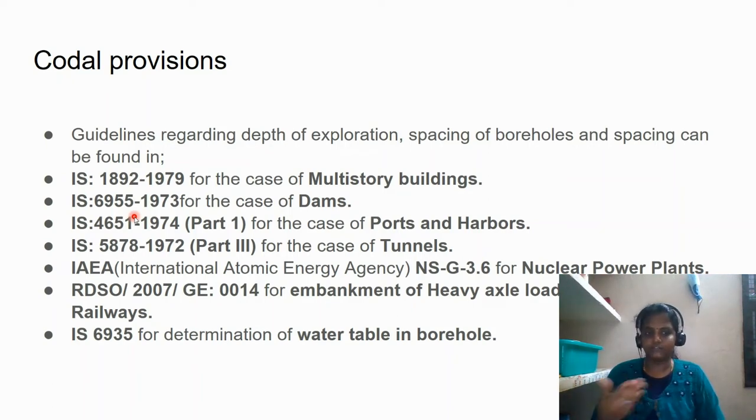And also, if you are able to encounter the same strata in three boreholes, of course you can stop at three boreholes. No need for the fourth one. So all these guidelines are subject to the judgment of the experienced engineer.